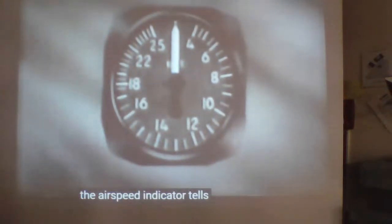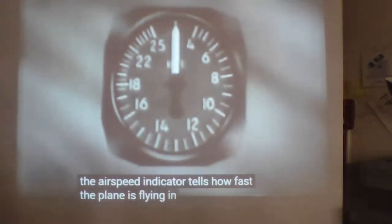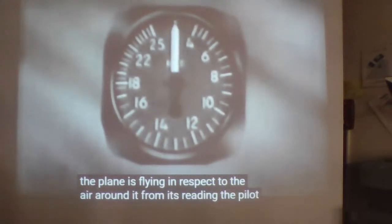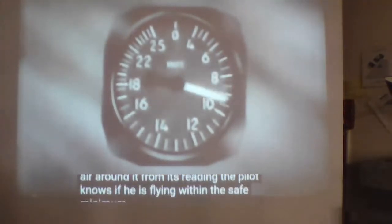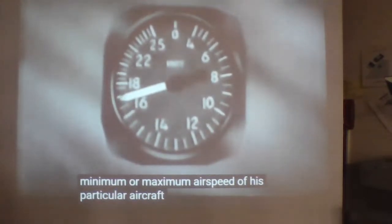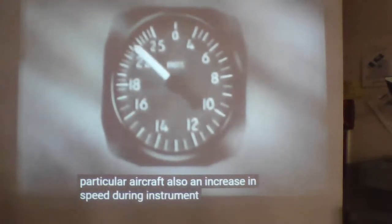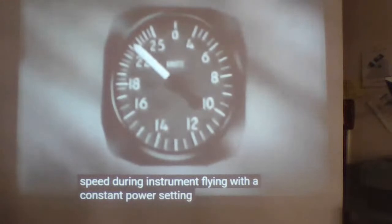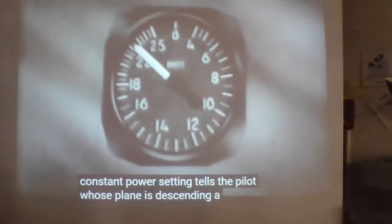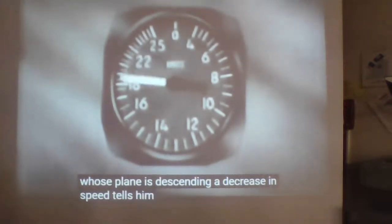The airspeed indicator tells how fast the plane is flying in respect to the air around it. From this reading, the pilot knows if he is flying within the safe minimum or maximum airspeed of his particular aircraft. Also, an increasing speed during instrument flying with a constant power setting tells the pilot his plane is descending. A decreasing speed tells him he is climbing.